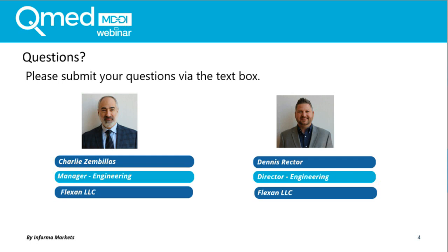So platinum is basically the standard nowadays. Peroxide is an older curing system. So generally, unless someone asks us for peroxide, we're going to be quoting platinum. Correct. Yeah, the only applications that we typically see in peroxide is when a customer has a material that's already been biocompatibility tested, that's in their list of approved materials. Generally, all new silicones are all platinum.